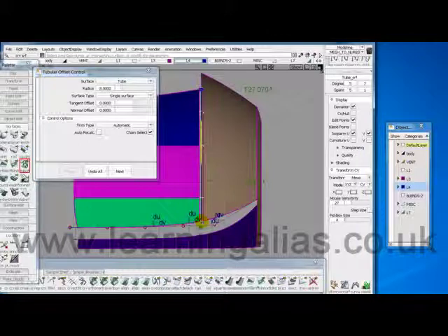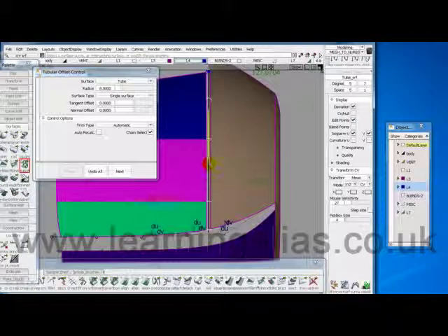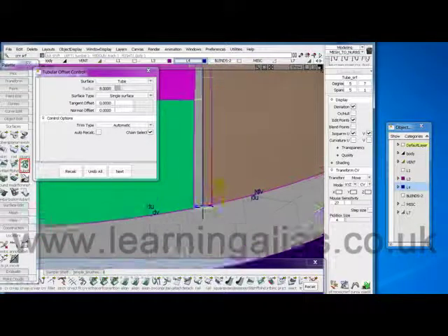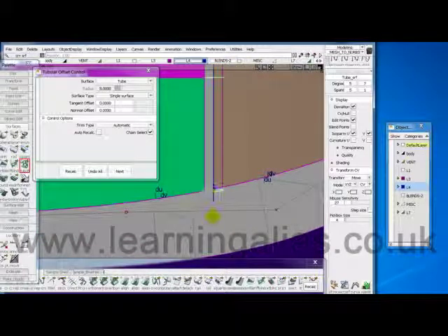Chain selected, so it's come all the way down here, and now I want to start flaring this out here, and I think I'm going to start from about, well, first of all, I'm going to get my width. Or can I maybe just bring that down there? I hit it there, produce another. So I've anchored that width by bringing that down there. Now I've put another manipulator here, and I'm going to zoom in and pick it so that it turns light blue, and then I'm going to scale it to that point there, so it cuts through where that construction point is and hit recalc.